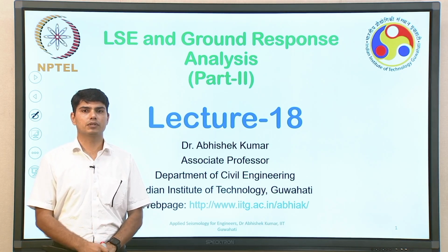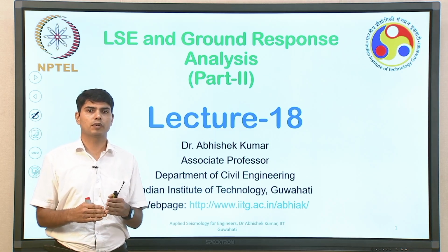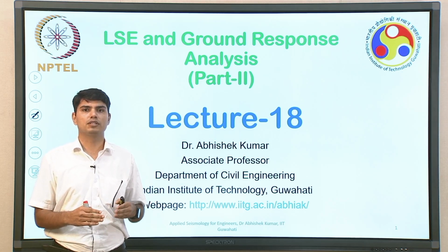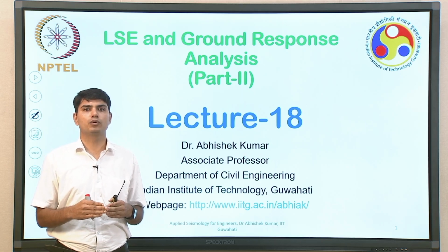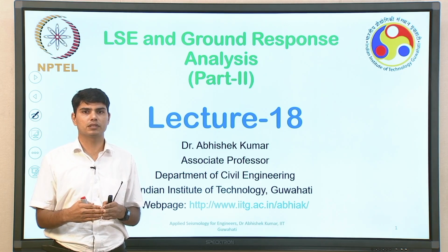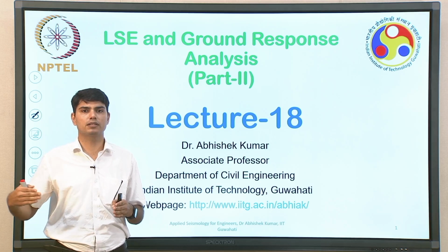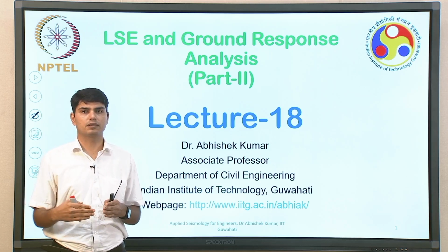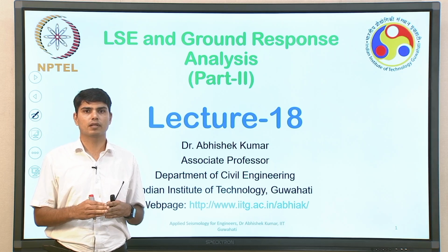What will be the governing equation? We discussed that when the primary wave is propagating, it is causing to and fro motion. When a shear wave is moving through a particular medium, it is going to trigger shearing in the direction perpendicular to the wave propagation. That means both in upward and downward direction as well as in horizontal direction. Both these directions will be perpendicular to the direction of wave propagation.